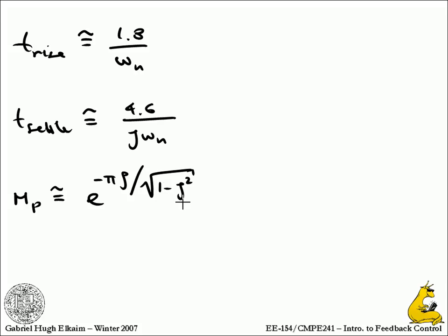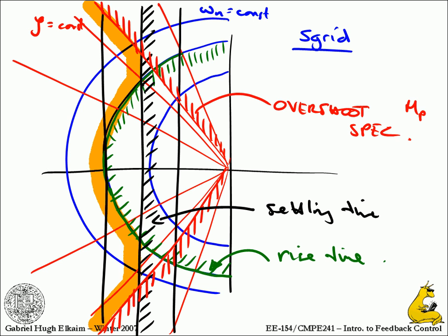Okay? So if we take all of that and we look at what the complex plane looks like, I'm not even looking in the right half plane because, well, those are unstable. All my answers are going to be here. So what I wind up with is some area within the complex plane where it's a good idea to put my poles. These meet my specifications.